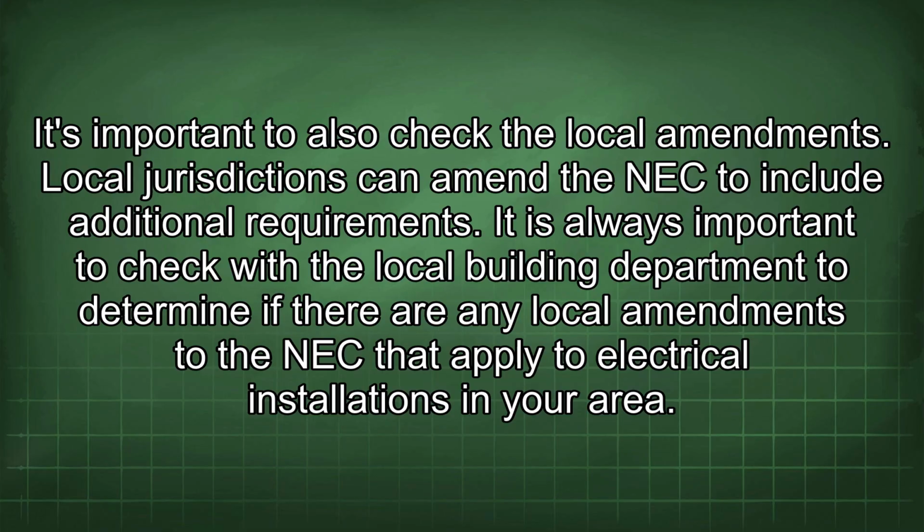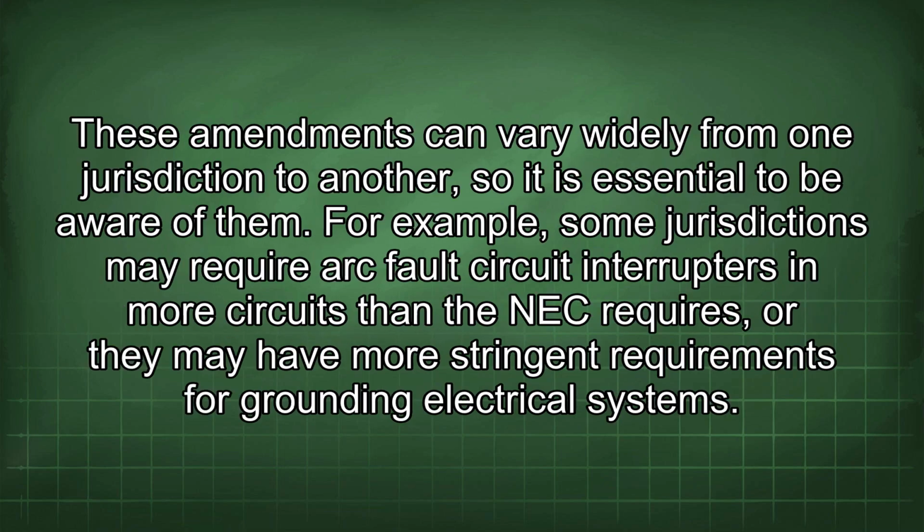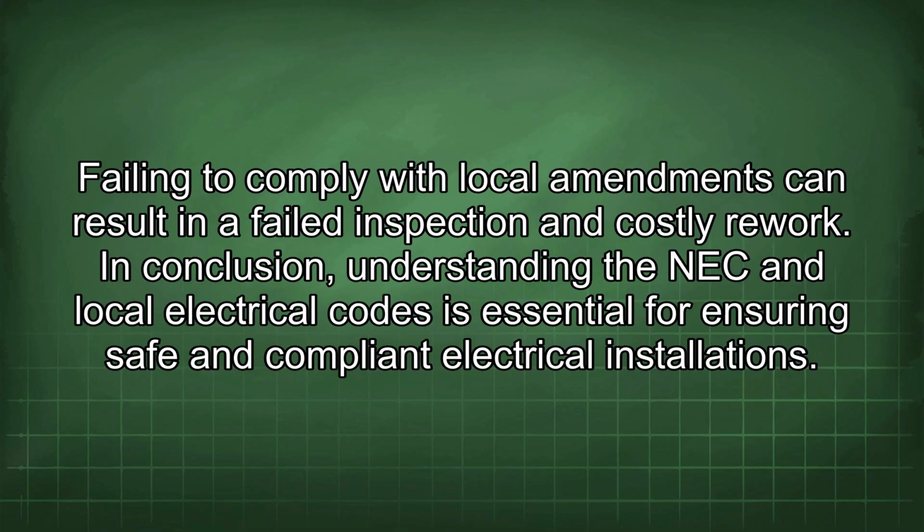It is always important to check with the local building department to determine if there are any local amendments to the NEC that apply to electrical installations in your area. These amendments can vary widely from one jurisdiction to another, so it is essential to be aware of them. For example, some jurisdictions may require arc-fault circuit interrupters in more circuits than the NEC requires, or they may have more stringent requirements for grounding electrical systems. Failing to comply with local amendments can result in a failed inspection and costly rework.